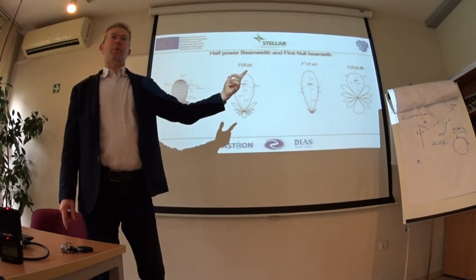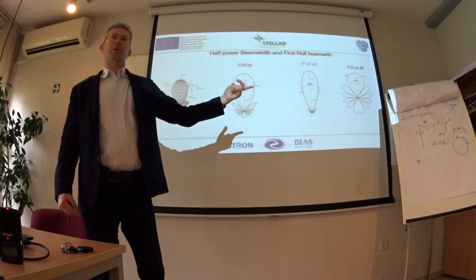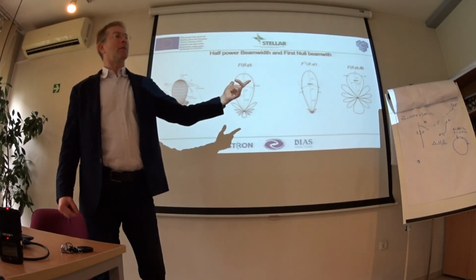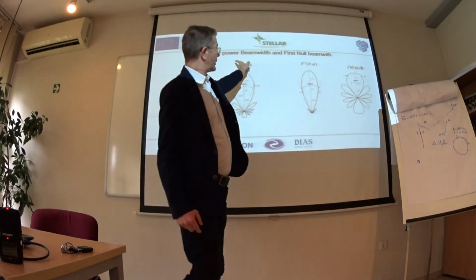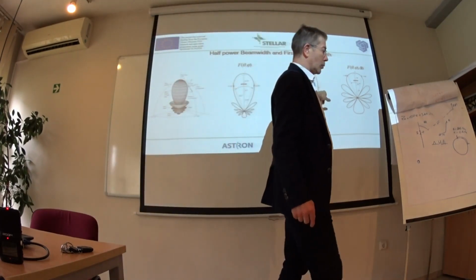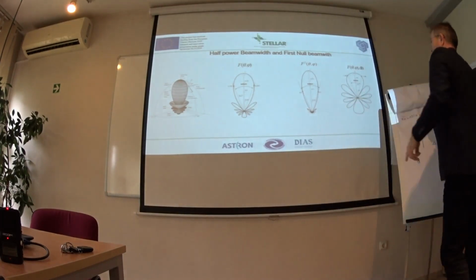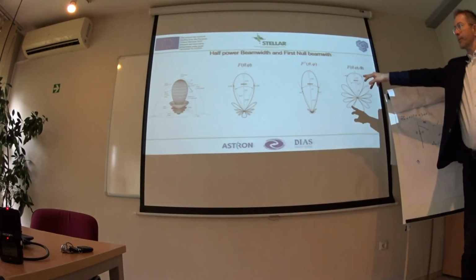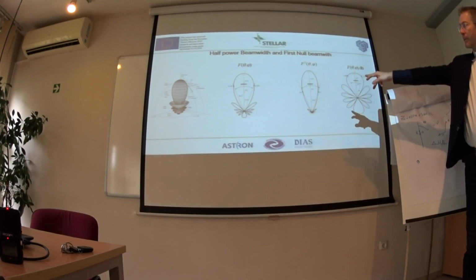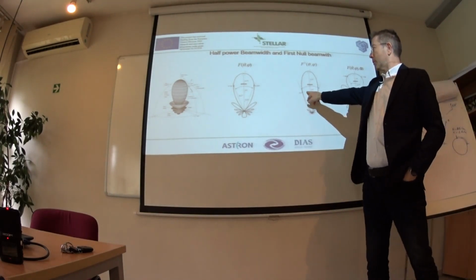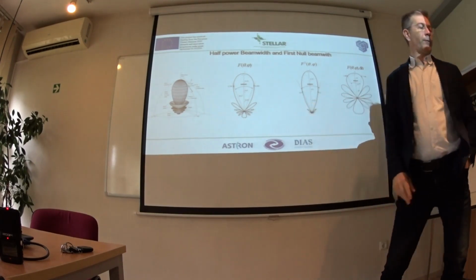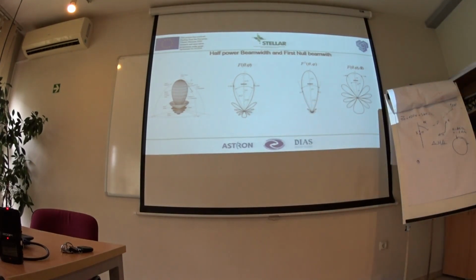Which antenna is more directive? The 20 degrees antenna or the 10 degrees antenna? 10, yes, because the pattern is narrower. And here, if we square the pattern and plot it into power measures, so field squared gives power, this will be the same angle but measured at the level 0.5. And that's why in the English literature this is called half power beam width.